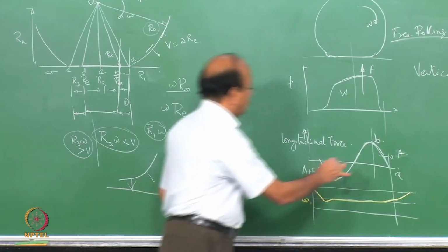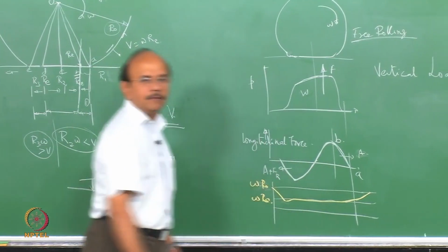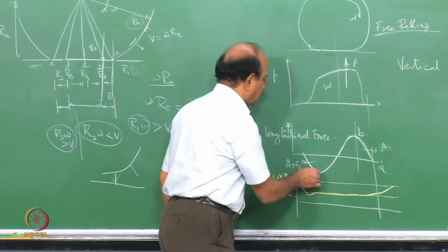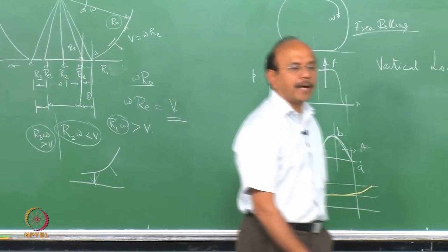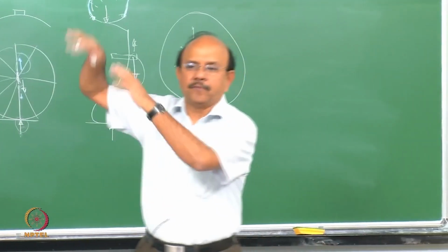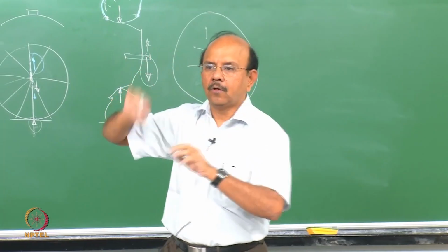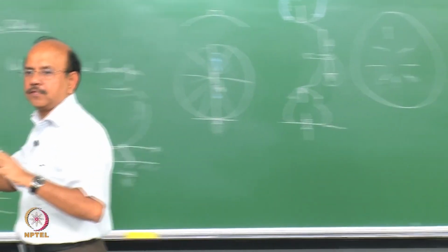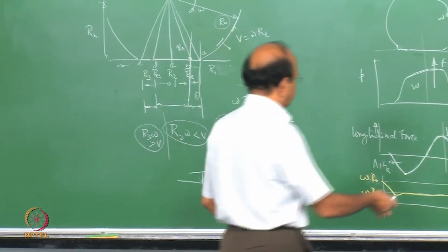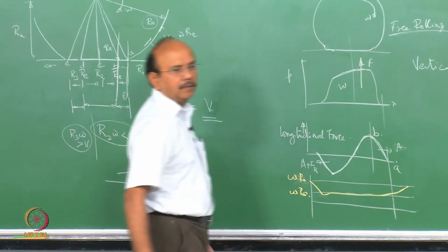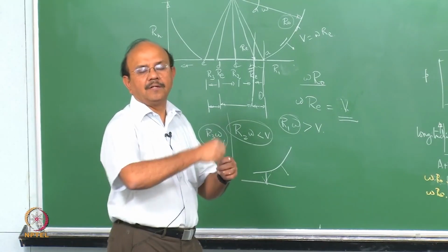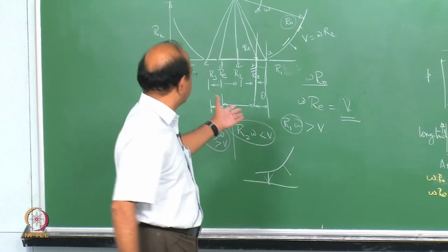Keeps building. And then again it goes in the opposite direction, and so it goes back to zero. So when the tread gets up from the tire and goes out, all those longitudinal forces have to go to zero. Right? That's what happens. All the longitudinal force, because it is outside the ground.